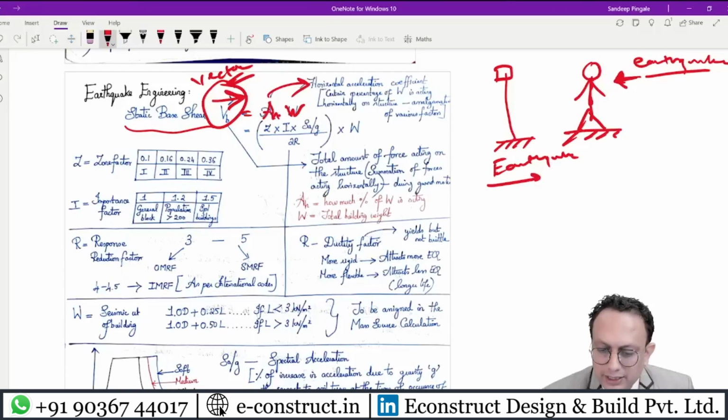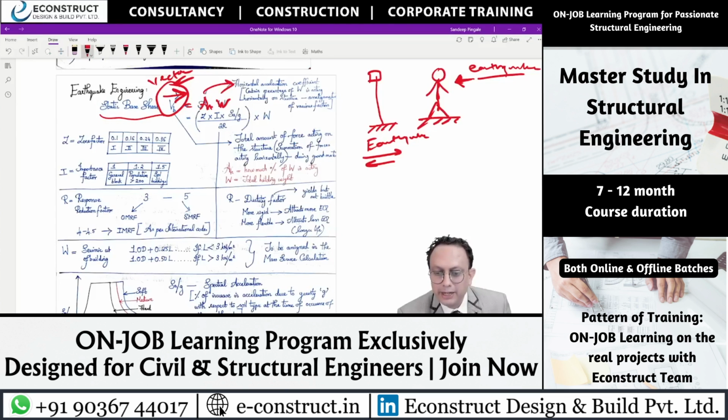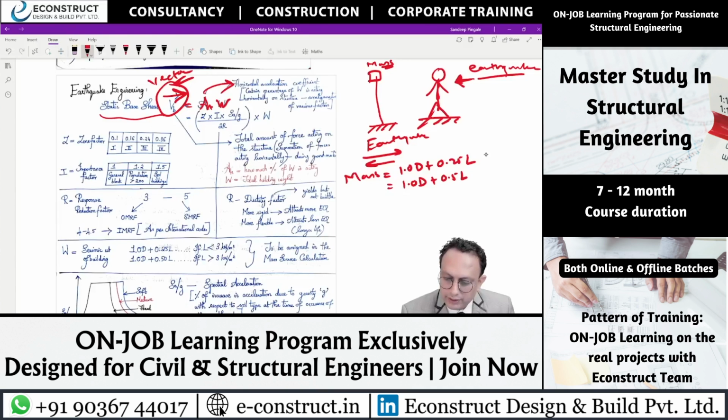whenever there is a ground motion acting onto the structure, it all depends on some particular factor multiplied by the seismic weight of the building. What is seismic weight? This is the mass. Generally, mass is equal to 1.0 times dead load plus 0.25 times live load when the live load is less than 3 kilonewton per meter square, and 1.0 times dead load plus 0.5 times live load when the live load is greater than 3 kilonewton per meter square. So this is basically the mass source that you will be collecting.